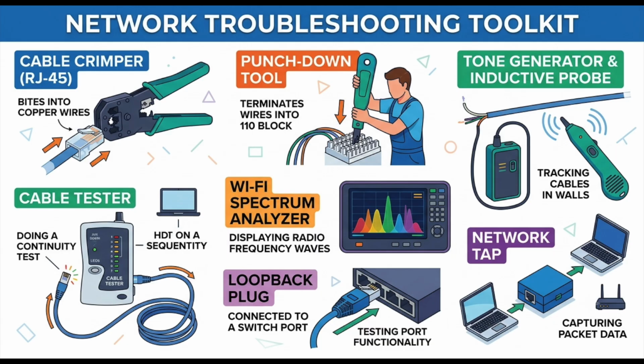You walk back to the massive closet of cables, turn on the probe, and start waving its tip through the bundles of wire. And it just detects that specific radiating field. Exactly. The probe acts as a tiny, highly sensitive antenna. Because it relies on electromagnetic induction, you don't even have to touch the bare copper. You just wave it around. You just brush the tip against the outside of the plastic jackets.